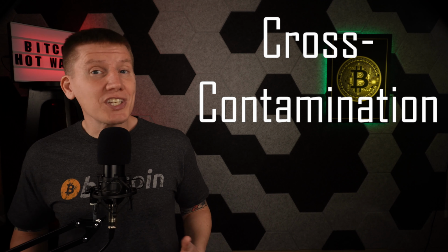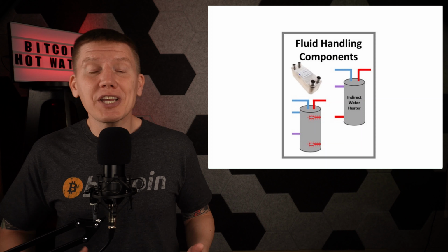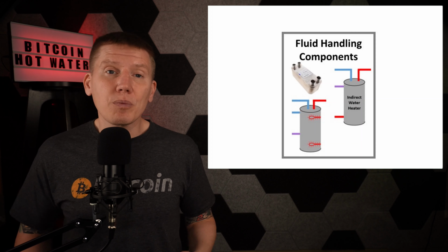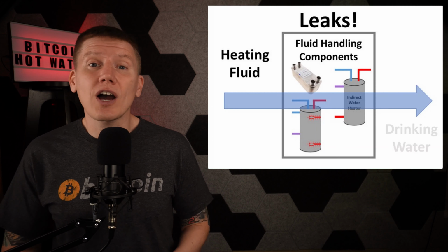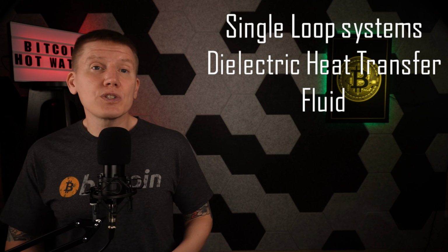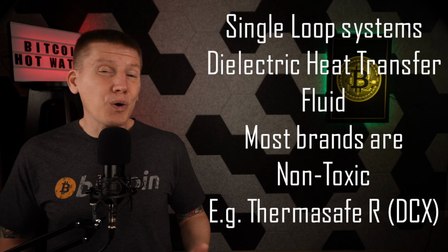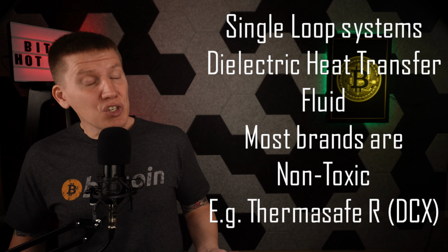And this brings up one more safety issue, and that is cross-contamination. There's always a chance that the heat exchanger, indirect water heater, or other components leak and allow fluid to move from the heating fluid into your hot water. If you're using a single loop system, most dielectric fluids are not toxic, so although this isn't a good thing, it shouldn't make you sick.